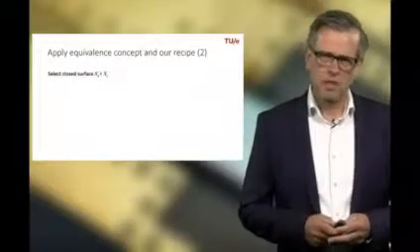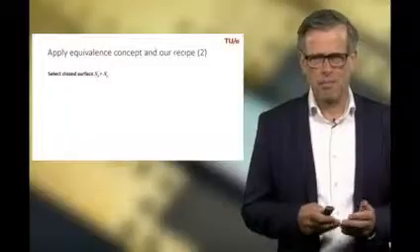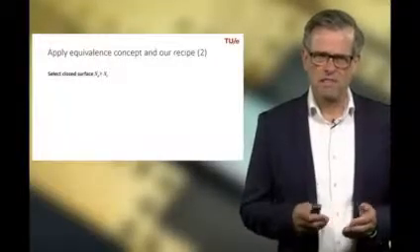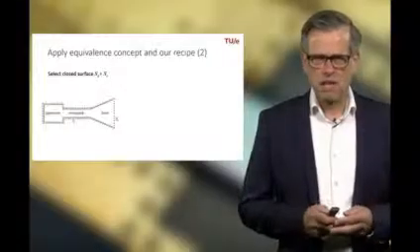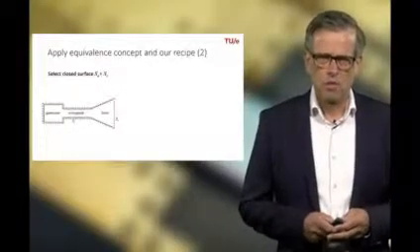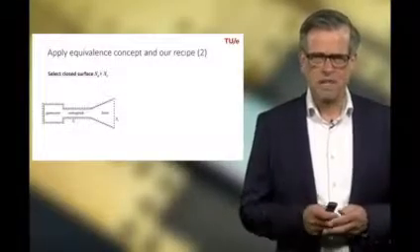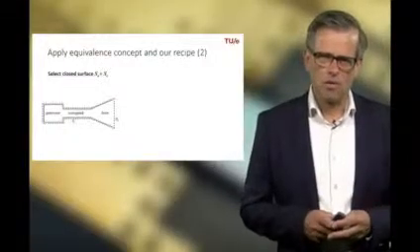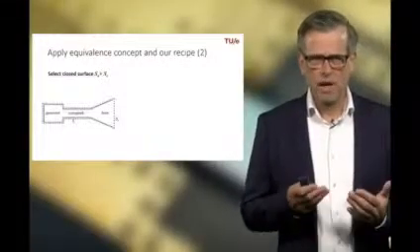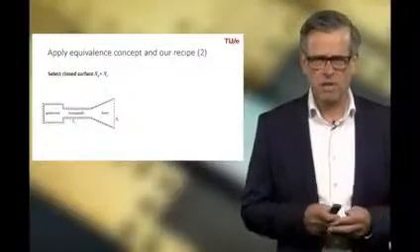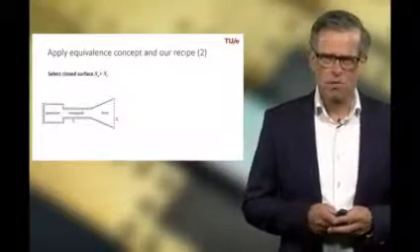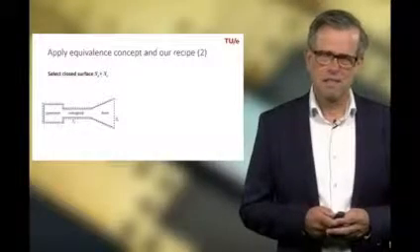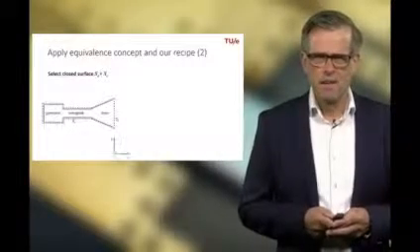In this case, we're going to split it in two surfaces, the aperture surface SA and the rest of the horn construction SC. This is visualized in this cross-section, where you recognize the horn with the radiating aperture and surface SA, and the rest of the horn, including the waveguide connected to it and the generator connected to it, is enclosed by the surface SC, and in total they make up the total surface S0.